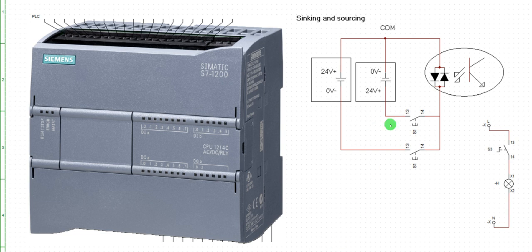Now, on some devices where you want to carry out your connection, they will put a warning that makes sure you follow the right sequence of connection because the system is polarized. Because of that, a mistake of interchanging negative and positive can damage some electronic devices. Because of that, some machines or electronic gadgets come with an inbuilt polarized device, a circuit inside the equipment that will correct the wrong connection of interchanging positive and negative.